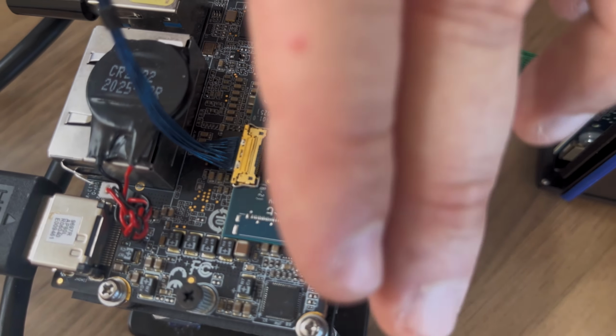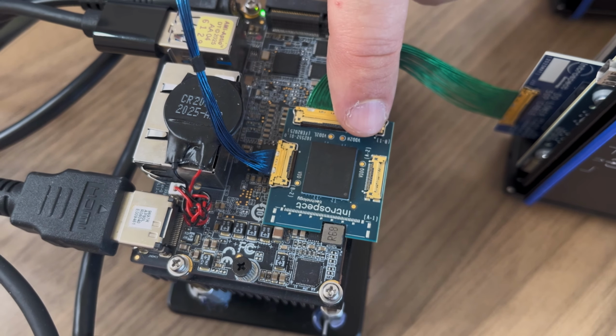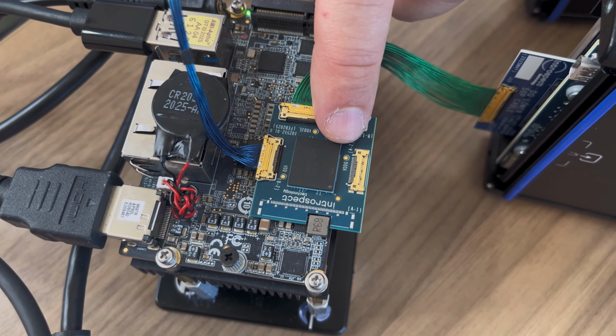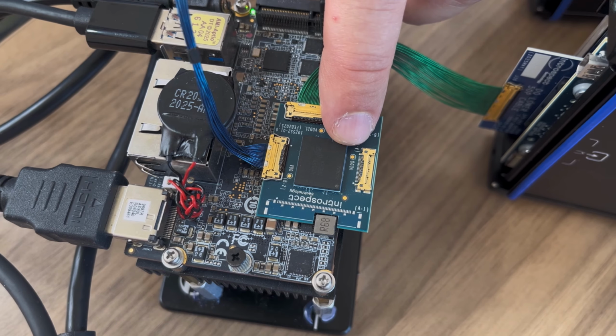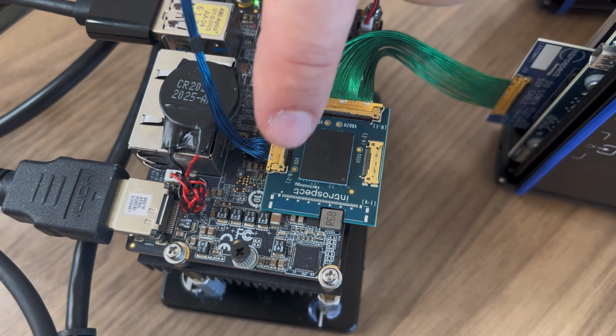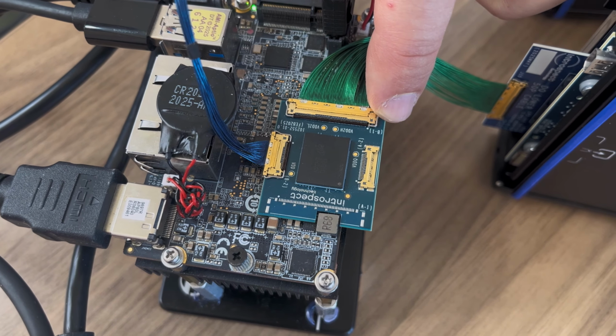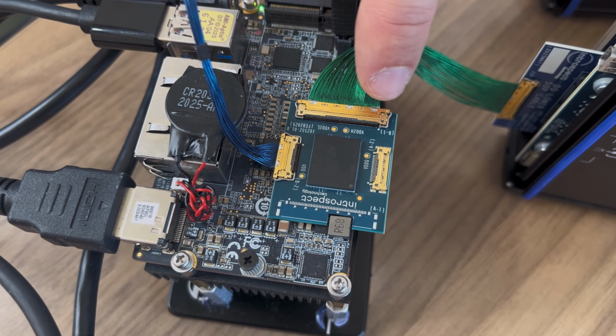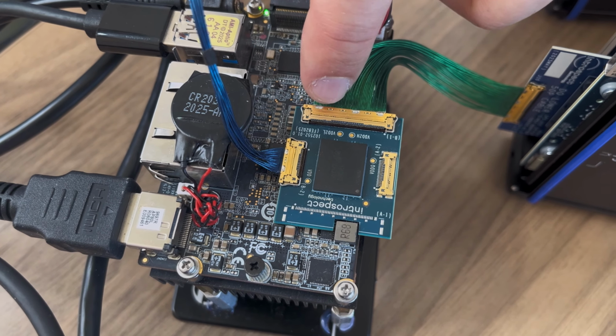So I'm showing the logic board for the PC here. And of course, of particular interest is the LPDDR5 memory. This is a 315 ball standard package LPDDR5 memory. And here it is sitting on top of the Introspect technology integrated tip interposer. This kind of interposer provides solderless access to all signals under the memory.